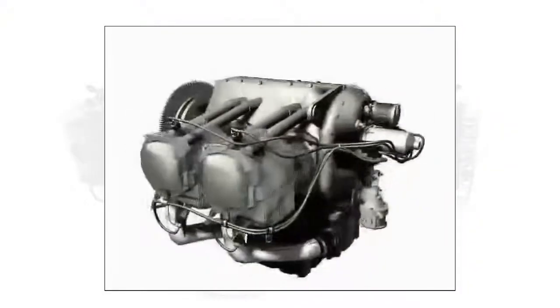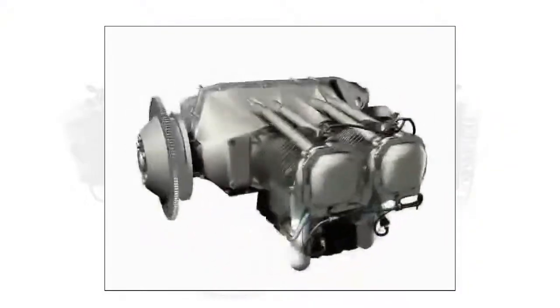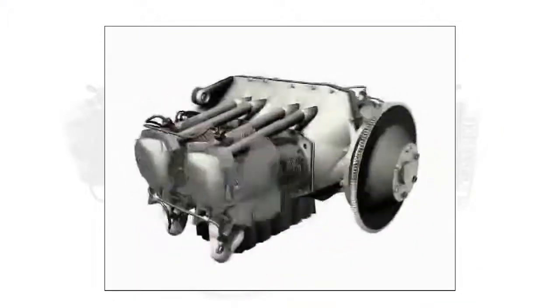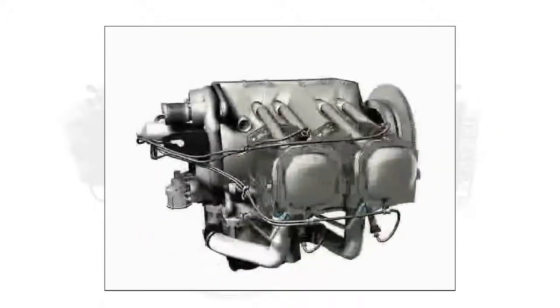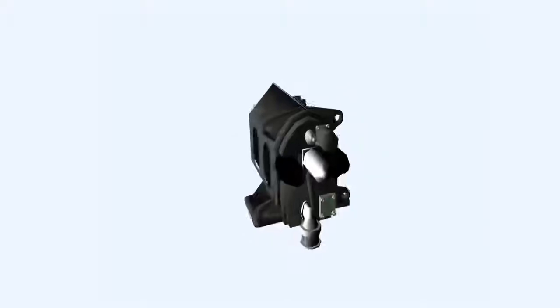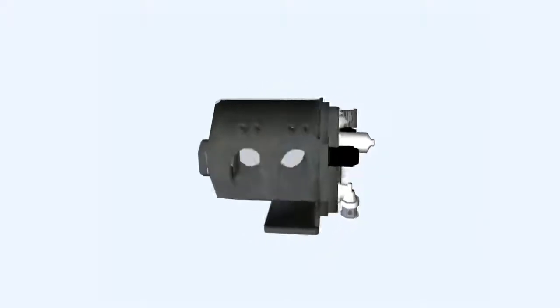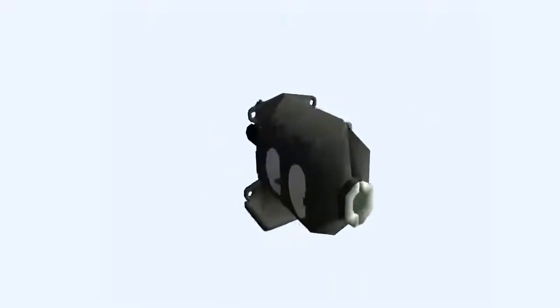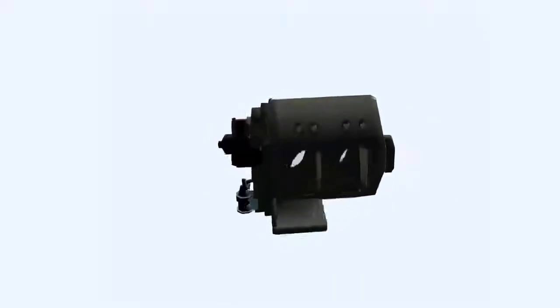The aircraft piston engine is made up of a number of component parts. We'll now describe the most important of these in some detail. The crankcase is usually made in two halves to make installation and removal of the crankshaft easier. It houses the main bearings for the crankshaft, supports the cylinders, and provides mounting faces and spigots for the attachment of the other main engine casings.